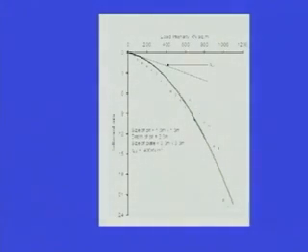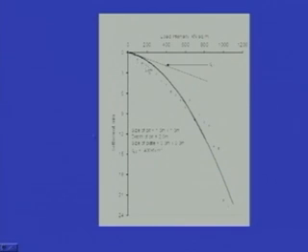Now, here you can see this is the load intensity versus settlement curve, a typical curve for the plate load test data. It is quite possible that these are all the observed points and a best fit is plotted for this particular data. From this plate load test data, which is the load settlement, either we can plot in terms of load and settlement or in the form of load intensity versus settlement. This can be used to determine ultimate bearing capacity of the plate.